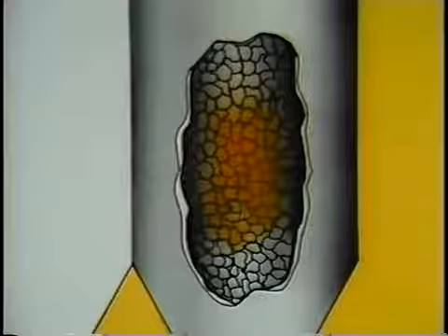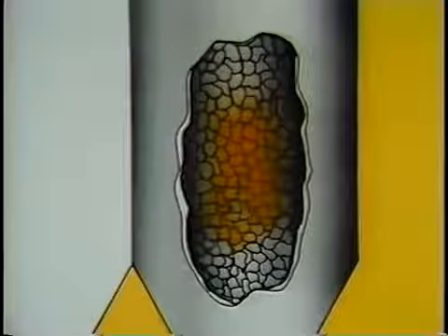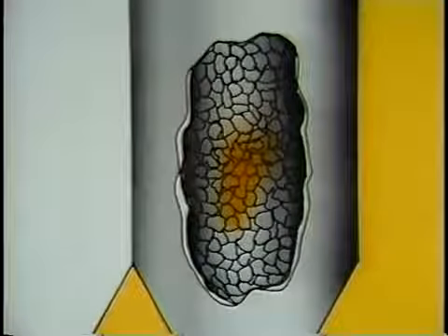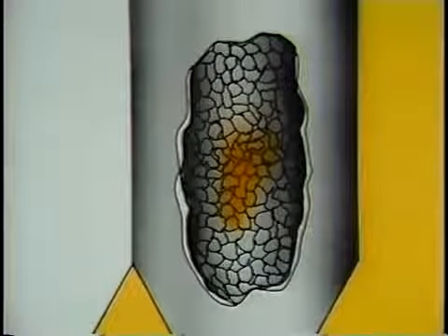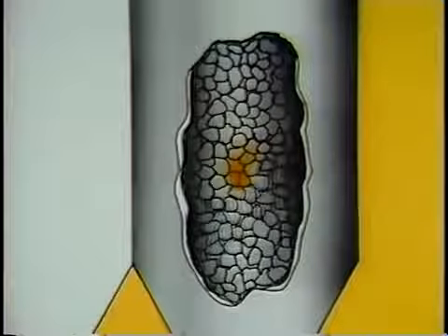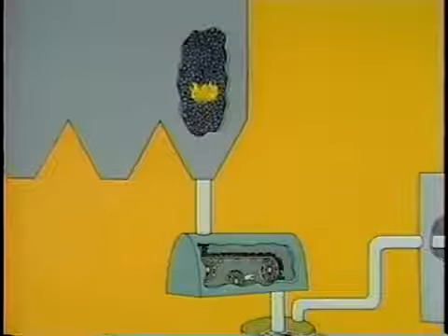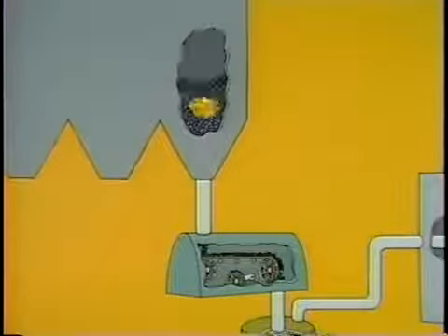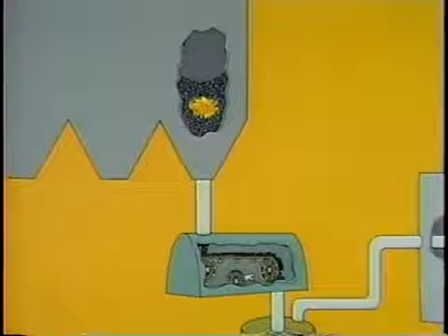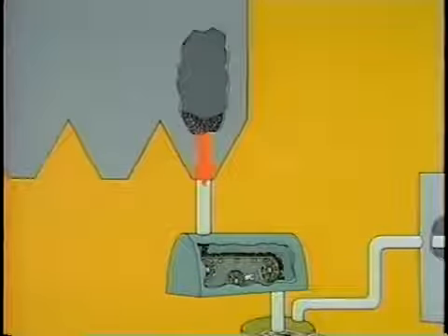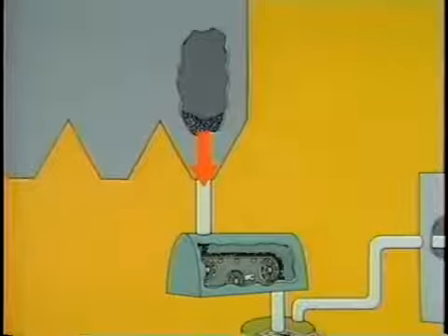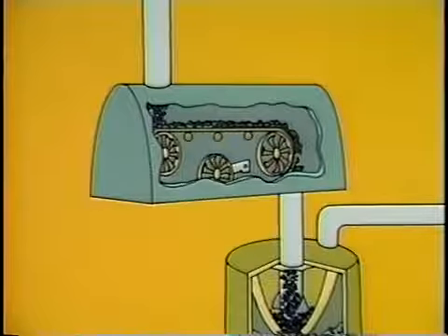Usually, as the coal flows through the bunker, the shifting of the coal compacts it and removes air spaces. This removes one of the requirements for combustion and may extinguish the fire. However, when an operator decides to burn the bunker empty, it's done with the understanding that the fire may be transferred from the bunker to the feeders and to the pulverizers. We'll look at feeder fires next.